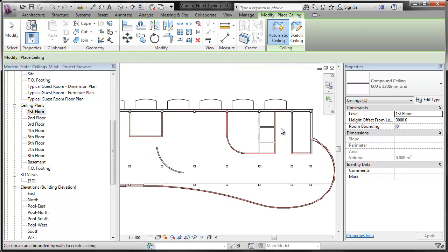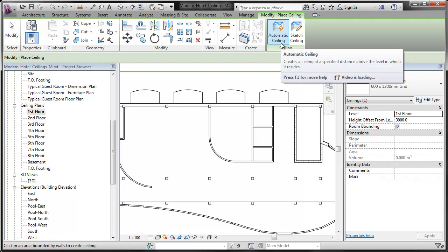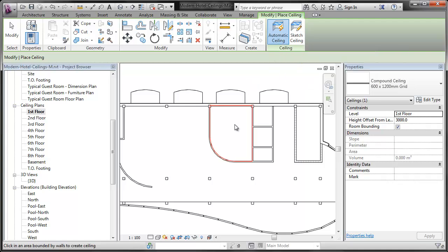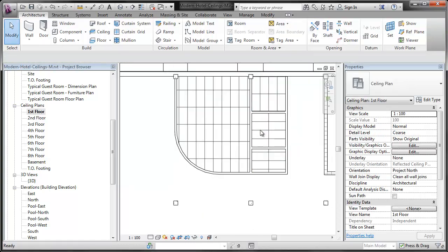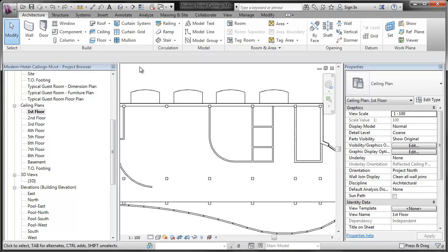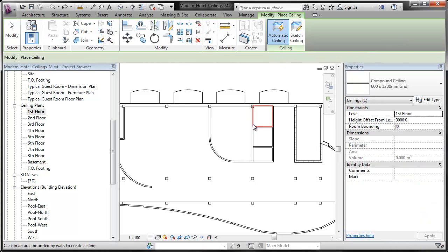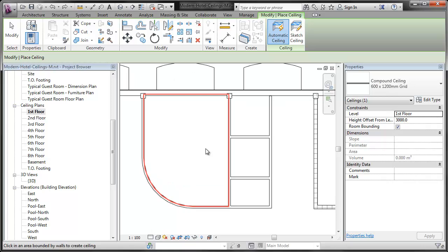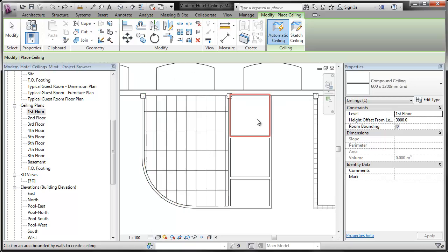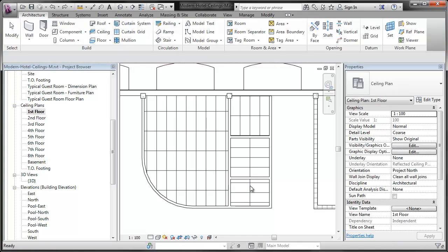and let's zoom in on here, and we want the automatic sketch, and let's pick those. Okay, so we go back through that again. We make a ceiling, automatic sketching. The little red box tells you what the extent of the ceiling is going to be. So we're just going to pick those, and then what we're going to do is we're going to hover over